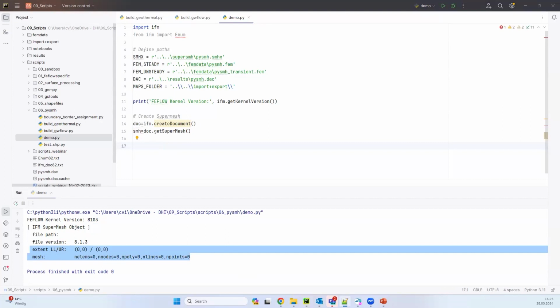What we recommend is that from the very beginning, you define what you want to do with the software. This is also an extension that we included since version 7.5. At the Supermesh level, you can set your problem class. There is a class called problem definition, which is also documented. I'm saying I would like to have a heat simulation, heat transport. These are the names of the variables. It's a steady state and it's a saturated system. Yep, so that's the definition.